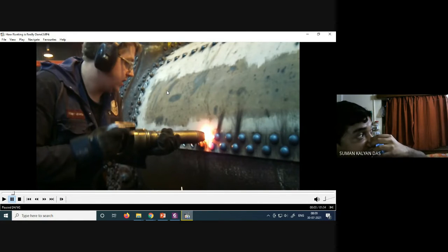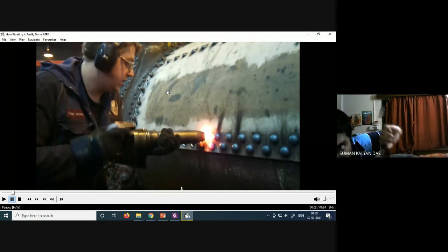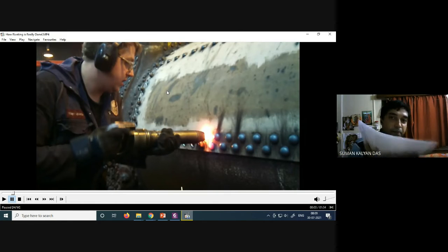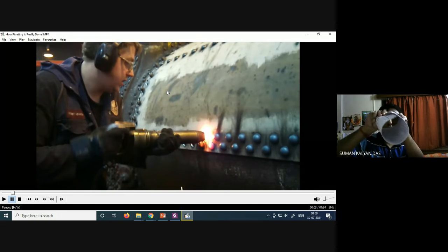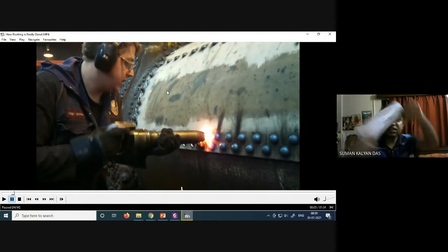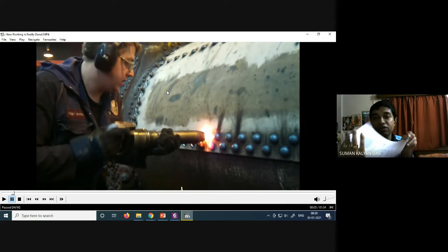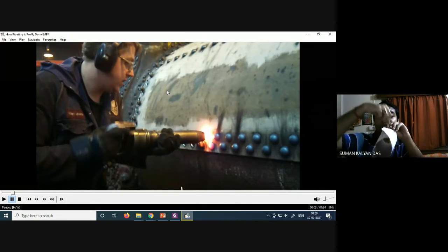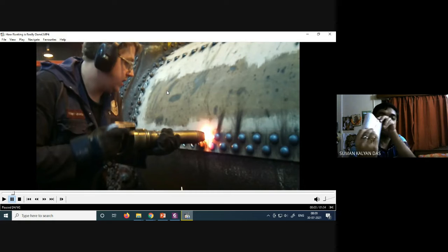So if you are making a huge cylinder like that, obviously you cannot make it as a single component directly. What you need to do is take a plate like this, and fold it, turn the plate like this, and finally you get a cylinder. So this is how you get the cylinder. As I am talking about making a cylinder from a plate, you can understand that at one point I have to join the two end edges. Otherwise this cylinder will not be in existence, isn't it?